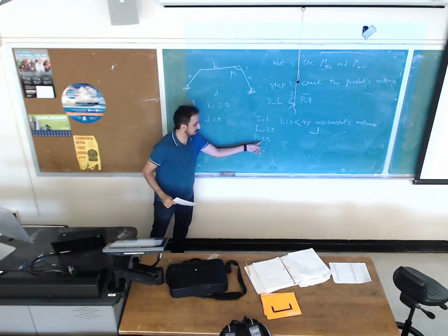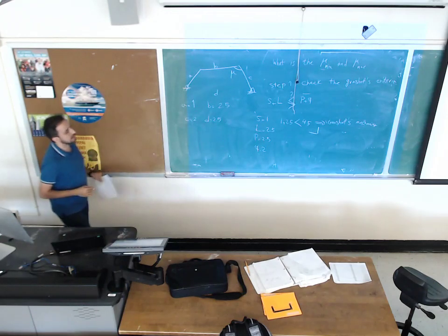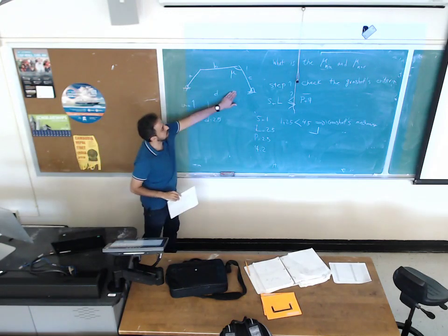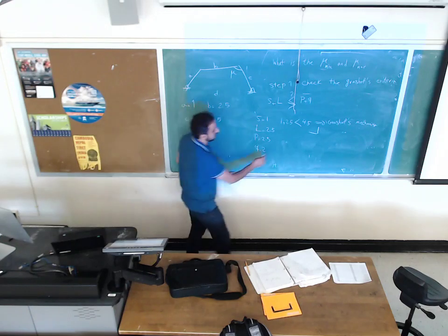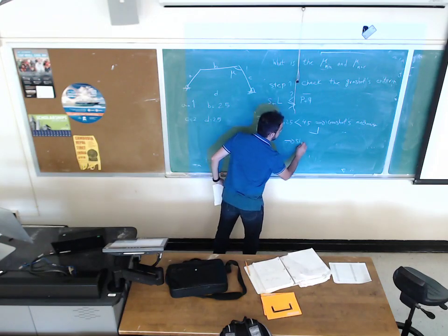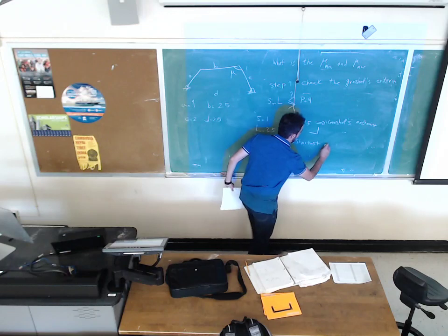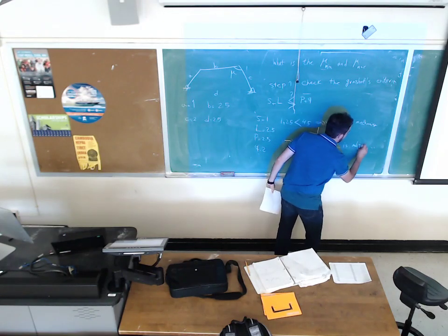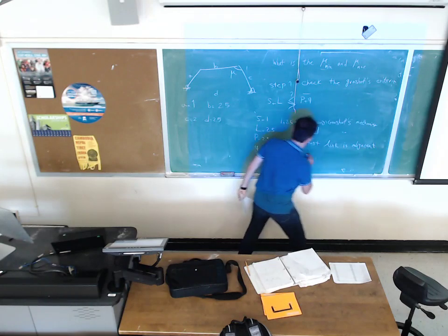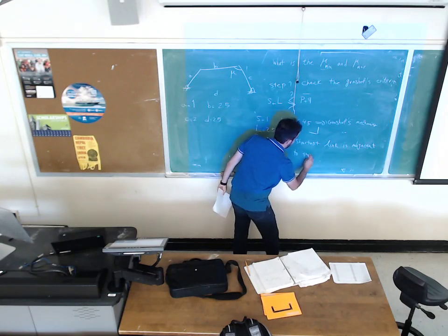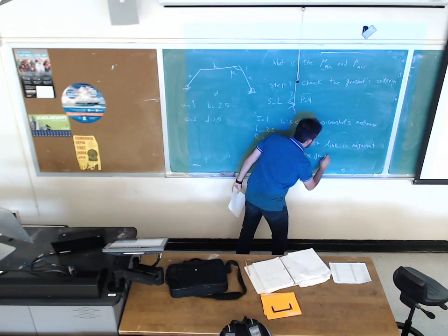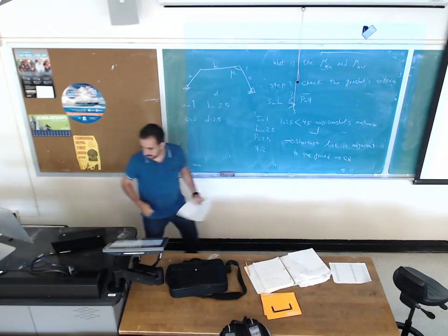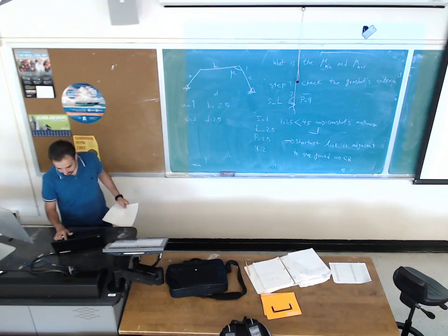This summation is less than this summation. Now, since the shortest link is adjacent to the ground, we have crank rocker. Shortest link crank rocker. So we have the crank rocker mechanism.